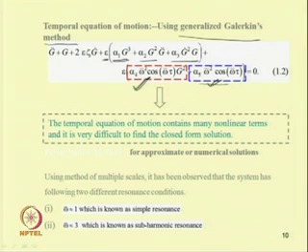a parametrically excited system. So, up to this, these are the linear terms, then we have cubic nonlinear terms along with a nonlinear term of quadratic type with parametric excitation, and we have a forced vibration term. As this temporal equation of motion contains many nonlinear terms, it is difficult to find a closed form solution, so one can go for a numerical solution.